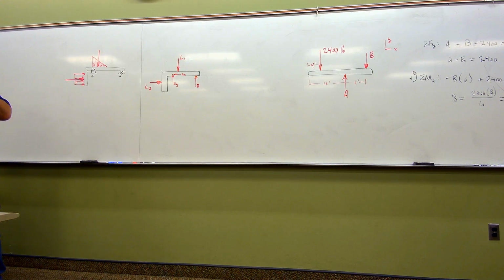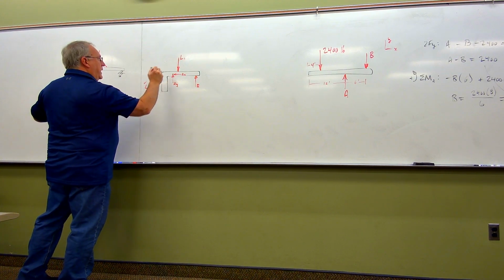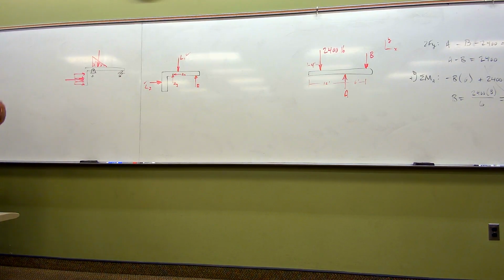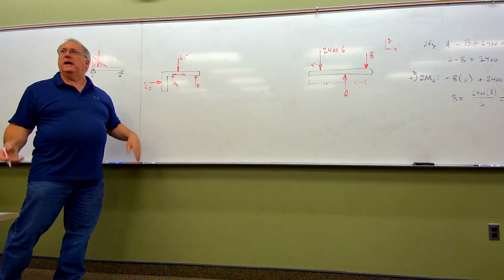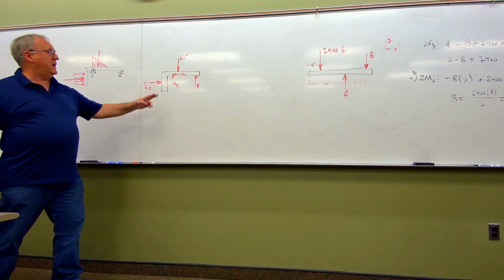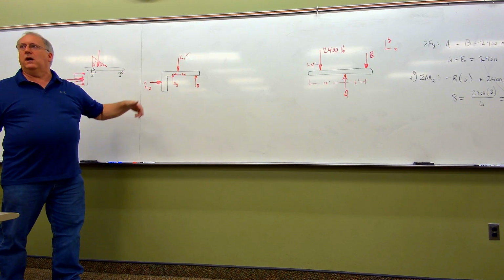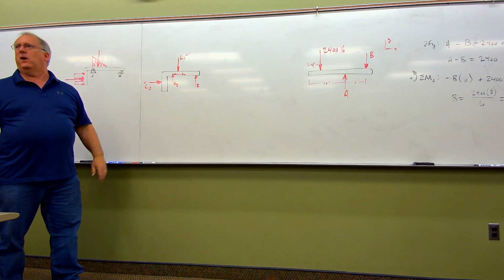So now if you look at what we've got here, folks, we would presumably know the value of L2. I mean, that's the whole idea. We get the value of these things, so we've got those two values. And now we're back to a free body diagram where, if I sum forces in the x direction, I'll have L2 minus AX, so now I know what AX is, right? If I sum forces in the y direction, I've got AY plus B minus that equals 0, and I can do a moment equation anywhere, get my moments, and figure out what all those are.